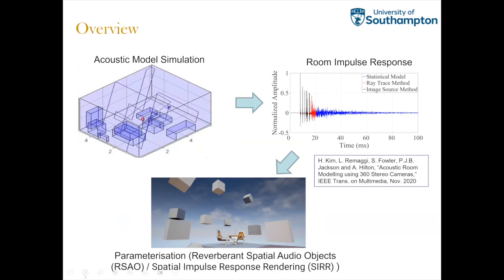And we also have to consider another function, HRTF, the head related transfer function. That is more like a personal function, because HRTF is different per person. It is the way the signal is delivered from the outside of your ear to your brain, because the shape of your ears, and the shape, length, and thickness of the inside of your ears are all different. So it is quite a personalized function, but we can measure it.